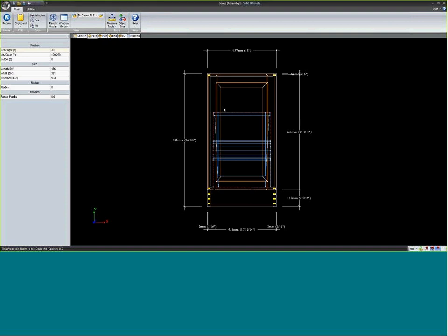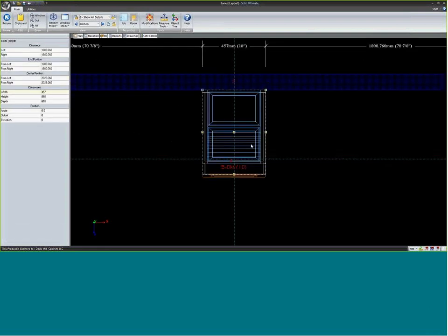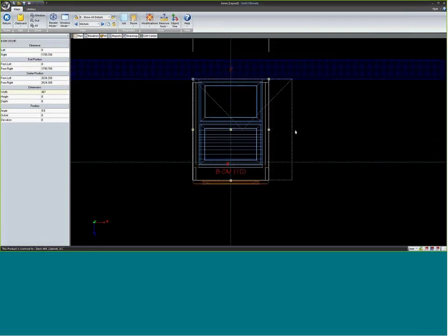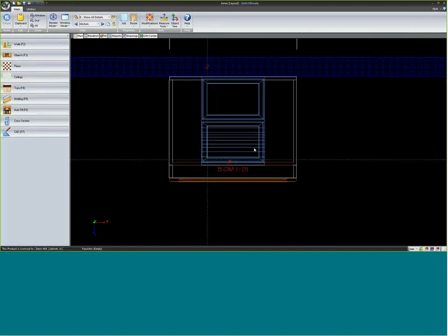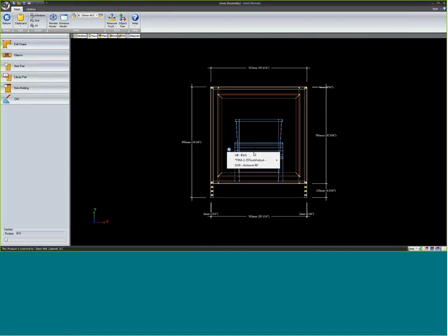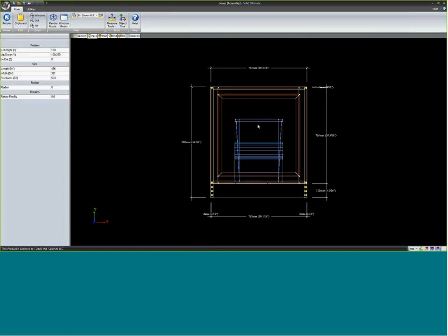So if I hit OK on this, it doesn't look like anything changed. I still see 30 millimeters in this window. But what's cool is now I can come out here and let's say I later change the width of this cabinet. So my trash bin stayed centered in that cabinet. It bases everything off of that formula. If I go back here and select the trash bin, now I'm at 193. 767 divided by 2 minus 381 divided by 2 will equal 193.